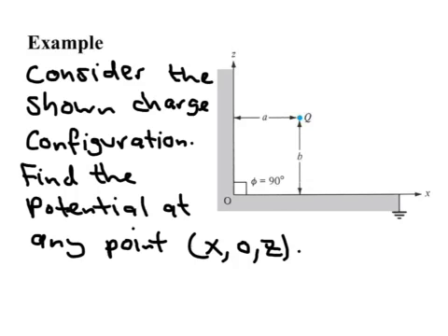Of course, this problem is extremely difficult to solve using normal techniques. If the charge was alone in free space, it's fine. The potential everywhere is q over 4 pi epsilon naught r. But because you have the charge close to two ground planes, the situation is completely different, because these ground planes must have 0 potential, but this charge is trying to make them have positive potential, because the potential here resulting from this one is Q over 4 pi epsilon r. You have to measure this distance. So how is this balanced?